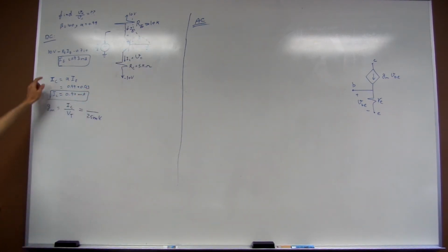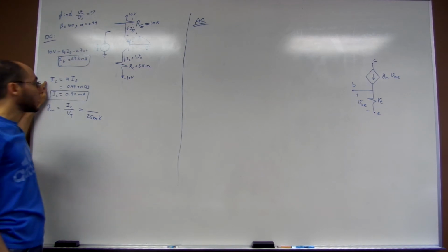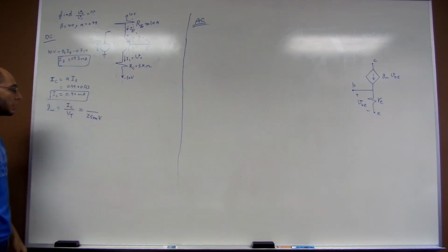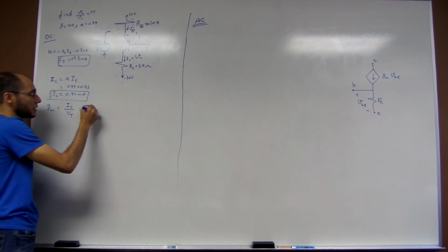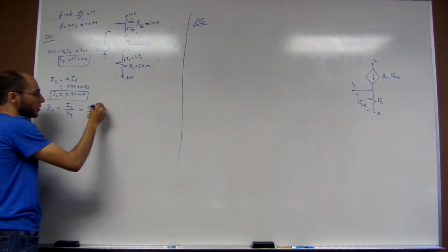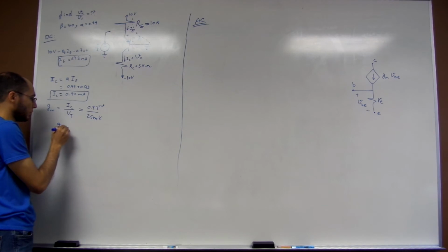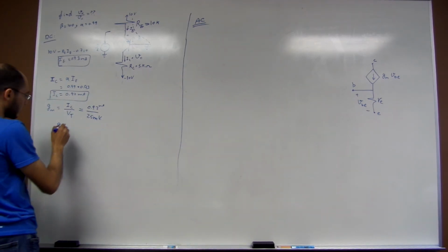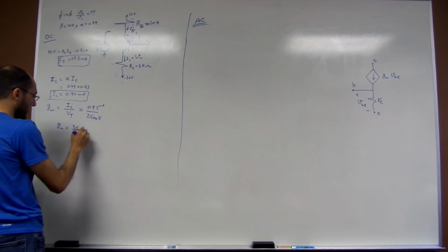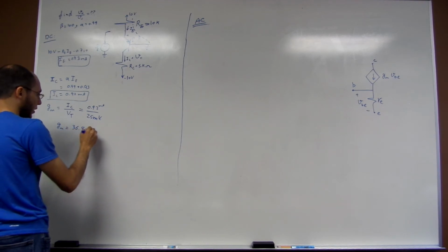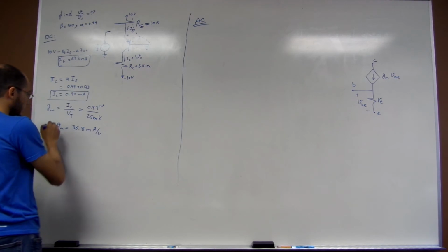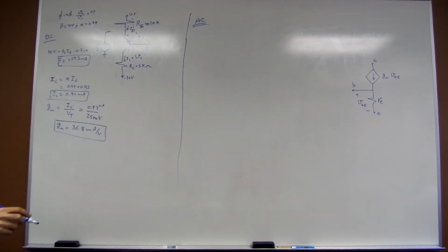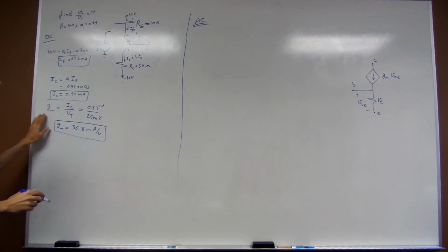Alright? So the IC becomes alpha multiplied by IE, okay, which means that IC could be obtained, and thus the value of GM becomes 36.8 milliampere per volt. Okay, 36.8 milliampere per volt. Okay, so that's the value of GM.